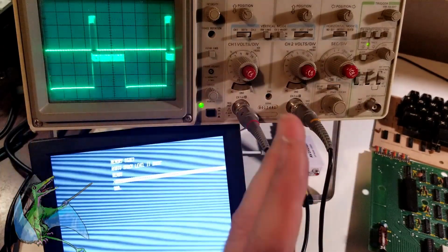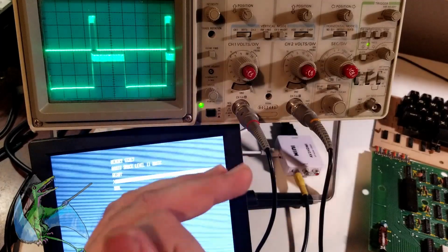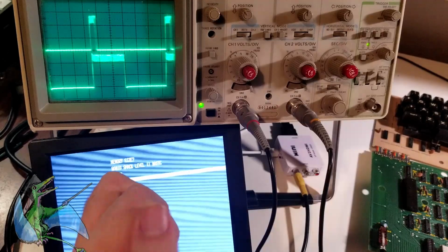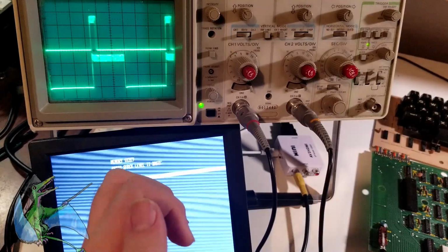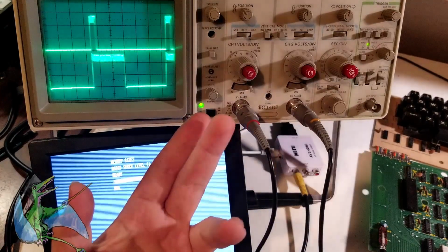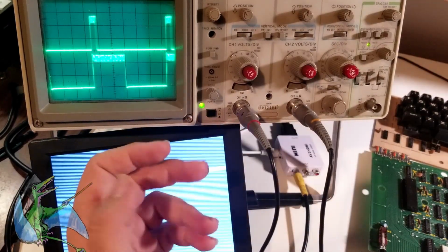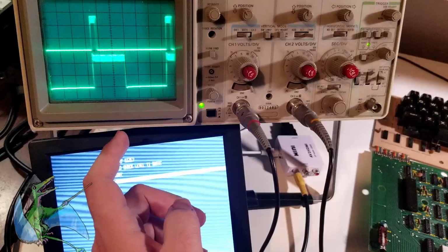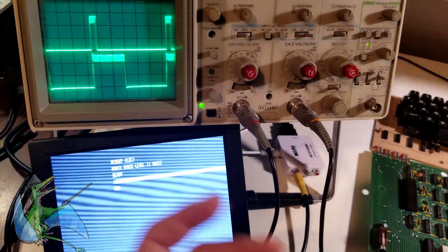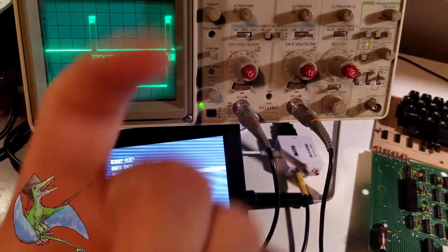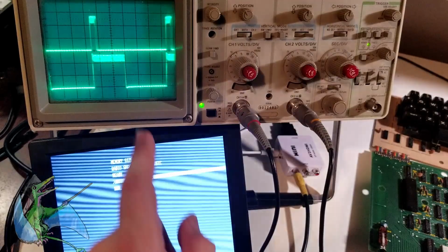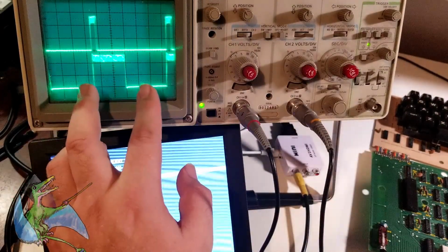The pulse is moving as you would expect based on the charge of these capacitors. So all the analog components seem to be working, except for the fact that the longer the capacitor needs to charge, the messier it gets. This also pretty much absolves the digital portion, because it's either on or off. If it was frantically dinging around, we would probably see it in this phase, and it's not. It's rock solid here.